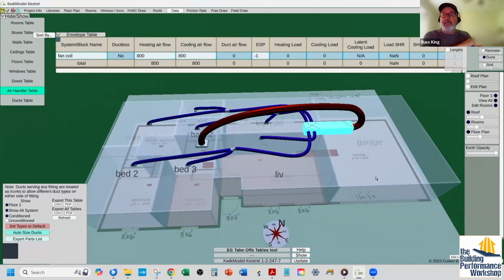And what we're finding is houses are getting really efficient. So these giant houses have these little tiny systems in them, and now the question is, is there enough air to even move the air around in the house? How long is it going to take for a CFM of air that comes out of the far room to get back to the air handler? And that's actually covered in a new manual called ACCA Manual LLH, which stands for low load homes. It talks exactly about if your system is so small compared to the size and volume of the house, is it going to mix well?